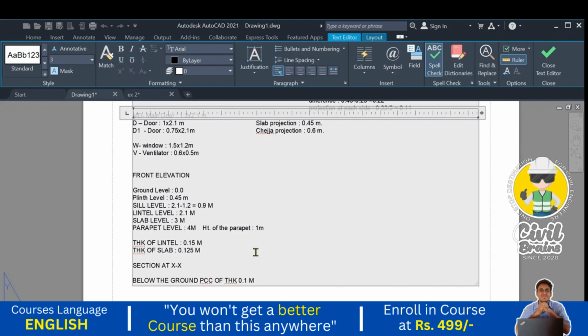Because to sustain the soil pressure also. At the same time, if any reinforcement is provided in the concrete, to avoid the rusting of the bar also, we are providing the PCC. And to avoid the dampness, that is important, we need to provide the PCC over there. So the first step is to provide the PCC. After the excavation we have provided the PCC.